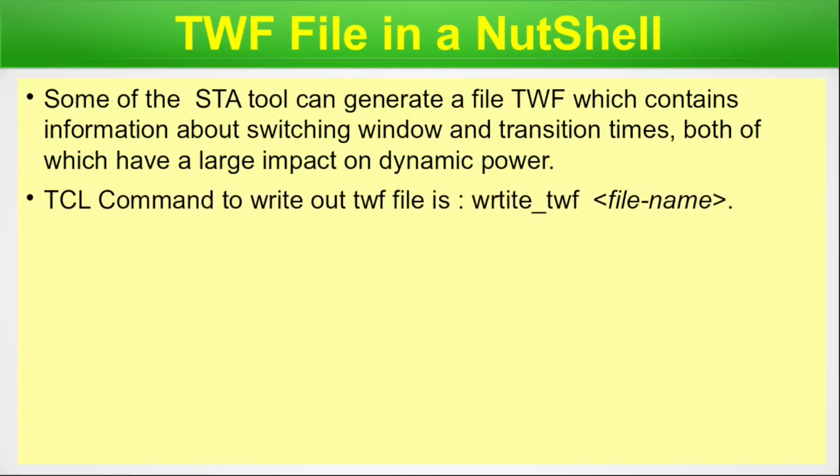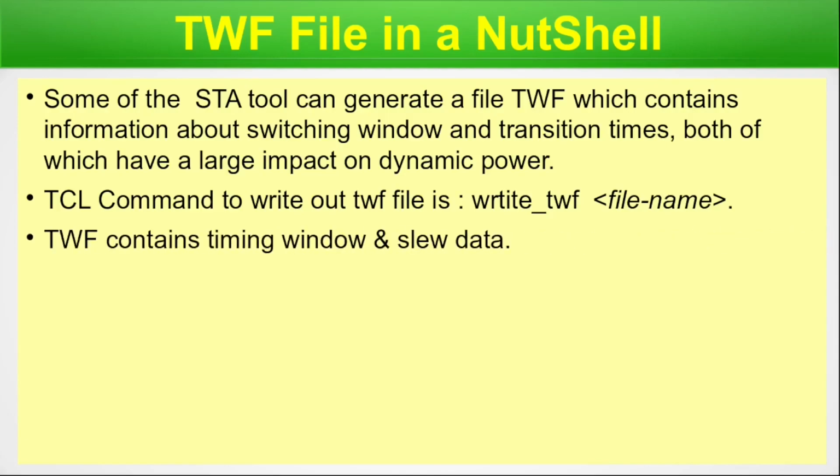The command to write out the TWF file is write_twf followed by the file name. This may be vendor specific. When I was looking for the TWF file, I came across that it is a very vendor specific file, and with that particular vendor you can write it with write_twf. TWF contains timing window and slew data.